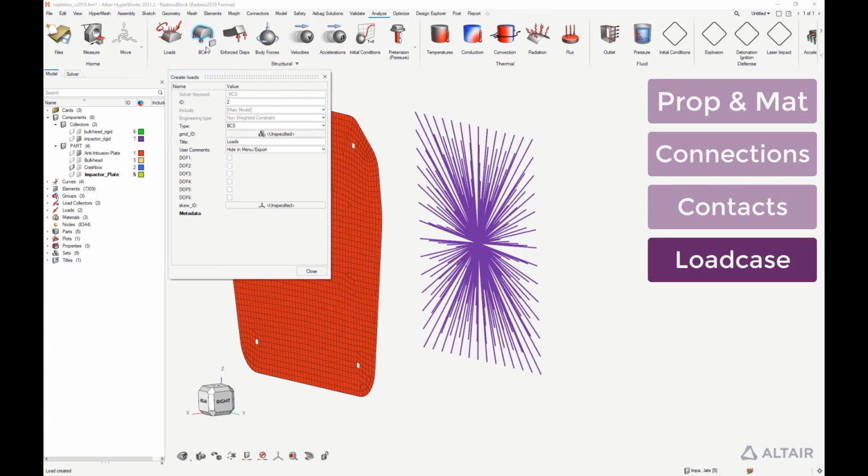I'm then creating a second boundary condition to limit the impactor's displacement. This time I'm letting free the translation along x-axis, and I'm blocking all the other degrees of freedom. I'm applying this constraint to the master node of the rigid controlling the impactor.